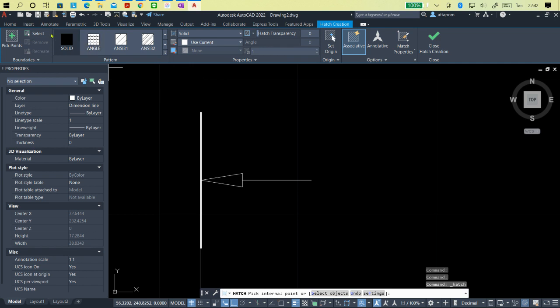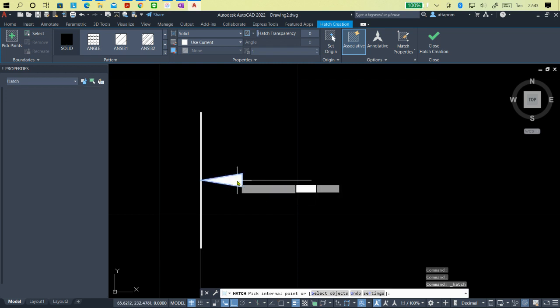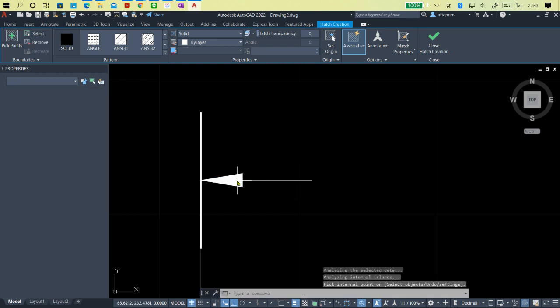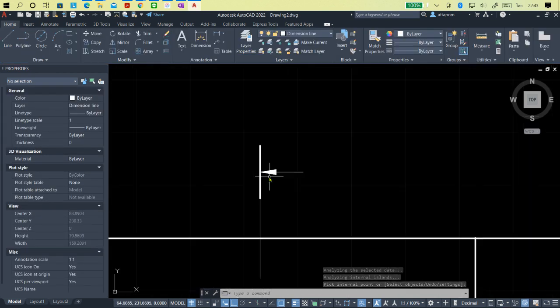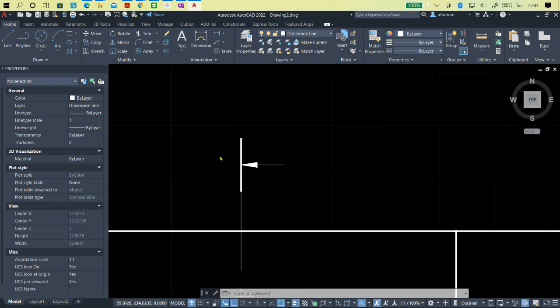In the hatchings, you press hatching and you can see the different style of the section line or hash style. You can choose anything here, but for me I choose solid. Okay, solid, and then you can put it here, and enter. Yes, an arrow is there.